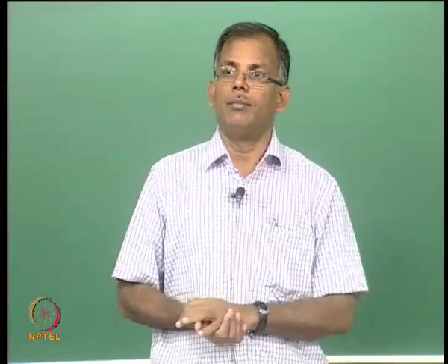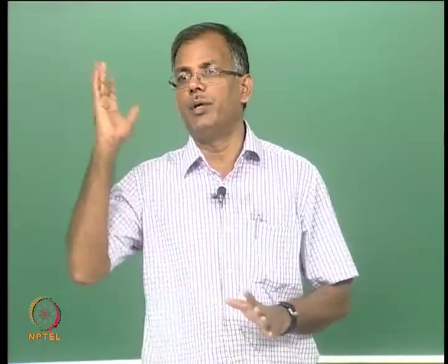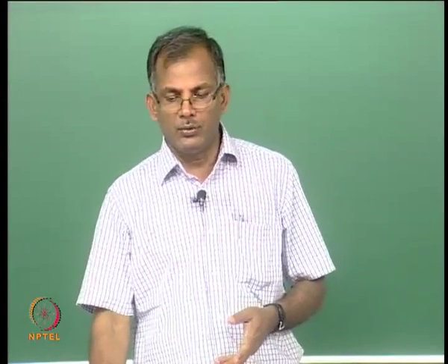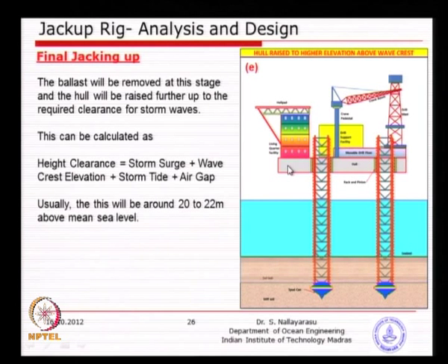it is going to come, may or may not come, the probability is 1 in 100, and you do not want to do that during normal drilling operations. You want to keep it as low as possible during drilling operations, depending on what the 1 year sea conditions are, and then whenever a survival condition is arising, then you raise the hull to a higher level. So, every time you will calculate storm surge, wave crest, typically 50-60% of the wave height.